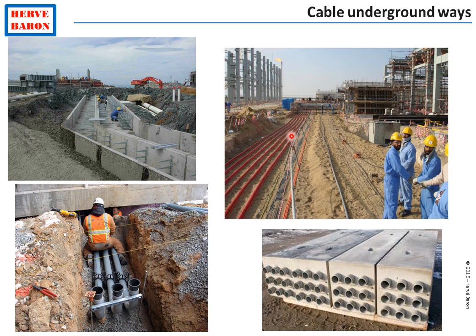When there is a paving, cables have to be run inside concrete cable trench with a removable cover. Underground cable systems also include duct banks for road crossing, as well as cable sleeves for the cables to go from the concrete cable trench up to the equipment through the paving.